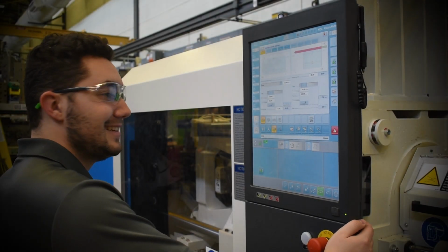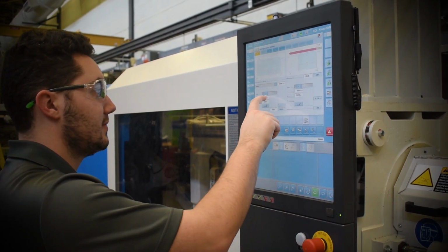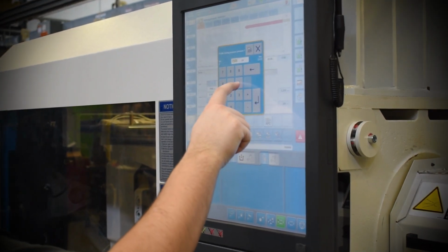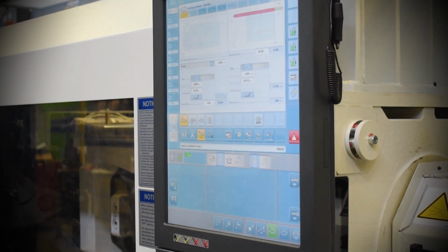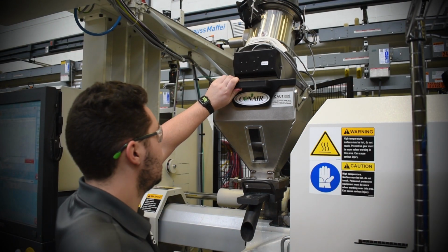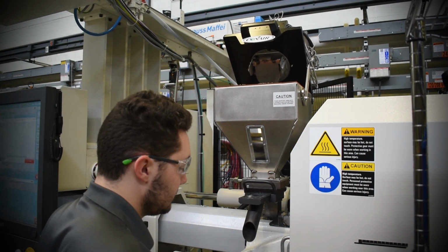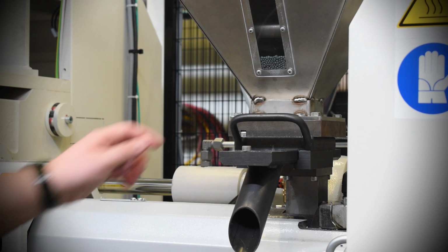For this project, the inclusion of D3 reduced the accuracy of simulations. However, we know that this is not always the case. It is possible that the pressures in the cavity needed to be higher to induce pressure-dependent viscosity on the real process. The characterization of D3 that was used in simulation also may not have been the best characterization, as it is not an exact science as to the best way to characterize the variable.